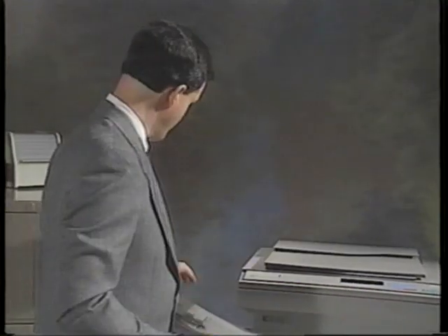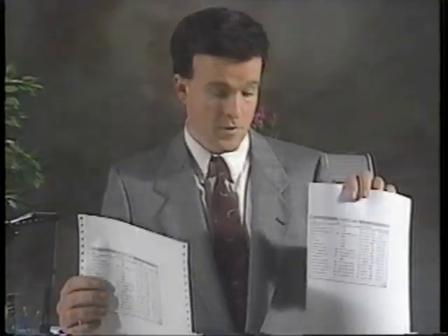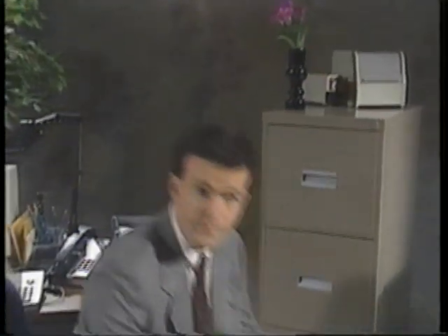Here's an original, and here's a copy. We've been looking at the technology that gets us from here to here. Earlier in this program, we examined the photoconductor, the material that makes electrostatic copying possible, and we've seen how the charge and exposure processes create a latent image, an invisible counterpart to the original you're trying to copy. The key word here is invisible. Just like an exposed roll of film, the latent image on the photoconductor needs to be developed.